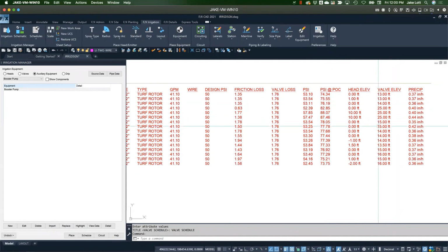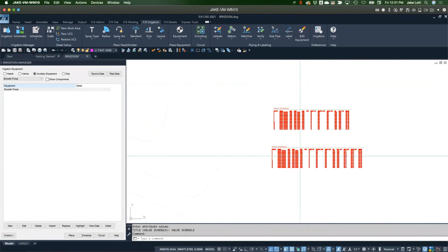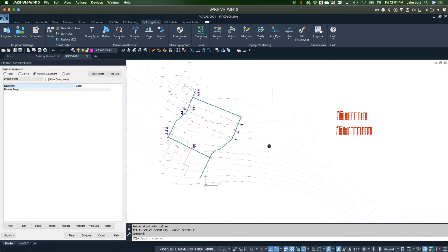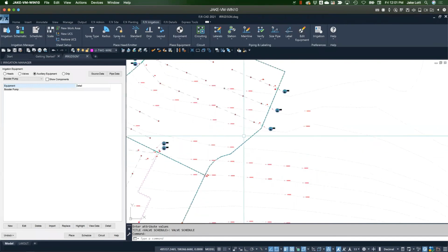But a really good snapshot to be like, hey, why am I losing 100 pounds of pressure? And you see that there's a 300-foot elevation difference between one of the things. It's really easy to start to cross-check that kind of stuff. But that now gives us a way better accurate sense of what the systems are going to actually operate on, based on the fact that we can simply integrate those in. So leave it there. Let's open it up for any questions you want to do.